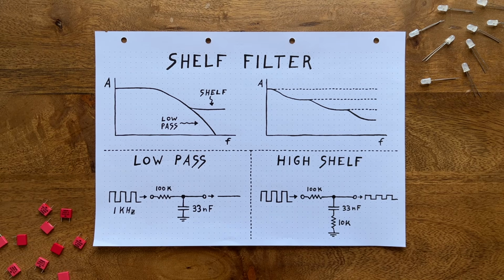Here's how it works. While the input signal is in its high phase, it pushes a very small current through the resistor and into the capacitor. Now, because that current is so small and the high phase is so short due to the signal's high frequency, the capacitor will absorb it without filling up noticeably, and the voltage above it will basically stay unchanged. Why is that?